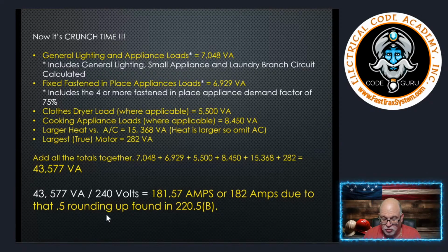43,577 divided by 240 gives me 181.57 amps, 0.5 or greater. We're going to round this to 182. So that is the actual load that I need to make sure I have a conductor sized for. Okay, so I have 182 amps.